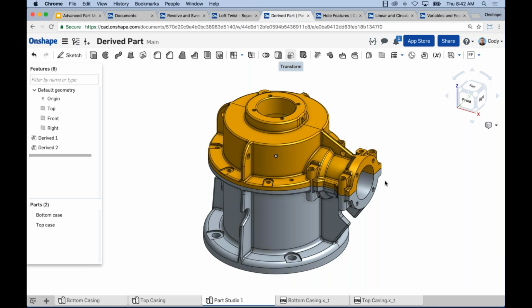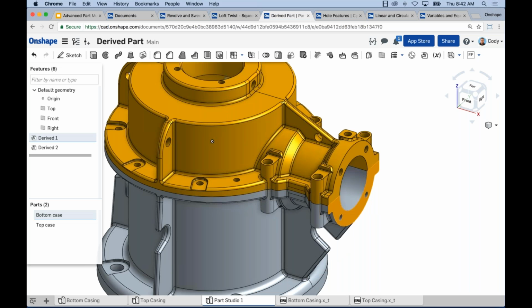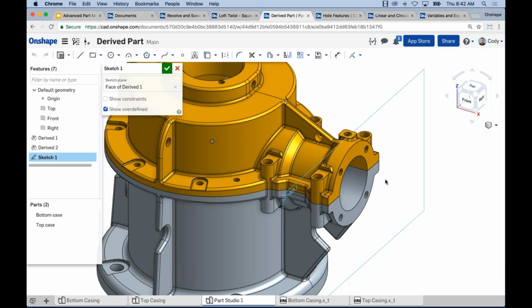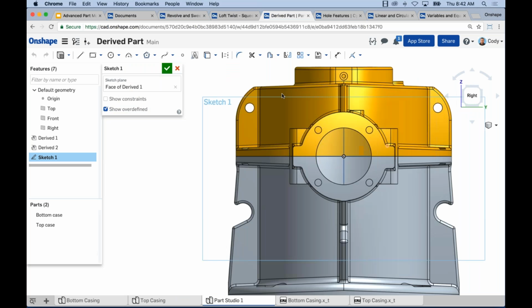Now what I want to do is build my part. Now that I've inserted both of the parts that I need and they're in the correct position, I can easily model around them, right? If I want to build a flange, for instance, I can do that. And I don't have to spend a lot of time measuring values, coming back to a blank part, adding the value, measure another value, come back to a blank part. You can kind of see the flow here. So I can easily select edges of the model, convert them with the use command, right? I can sketch geometry in and add constraints relative to it. So it just makes it very easy to create my part with respect to this imported file, right?